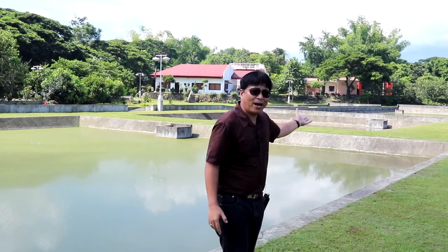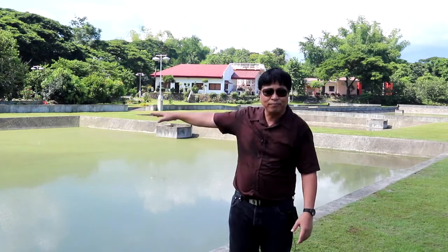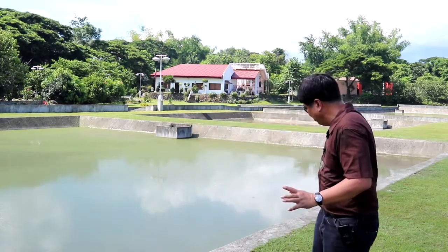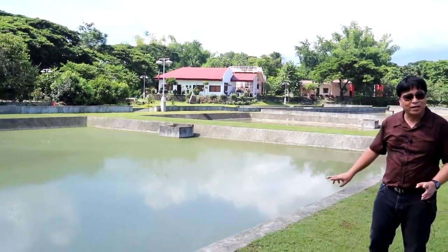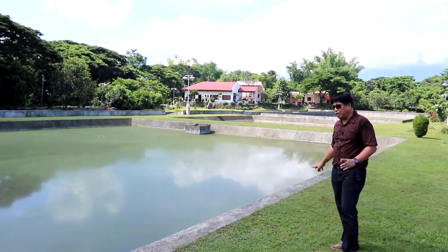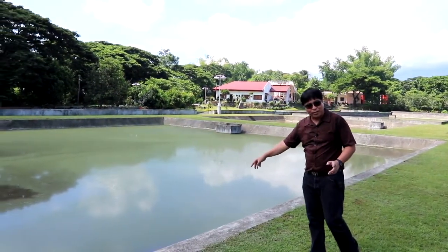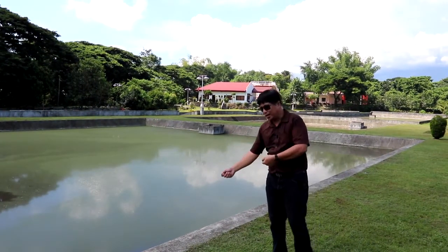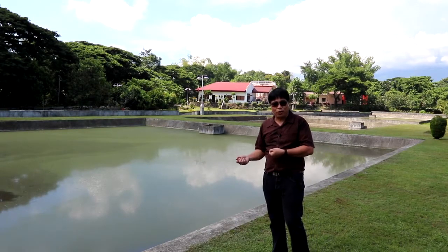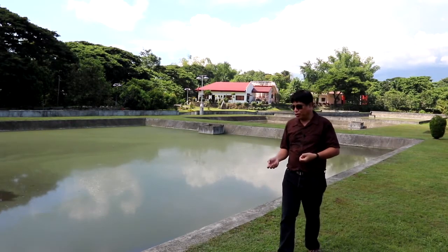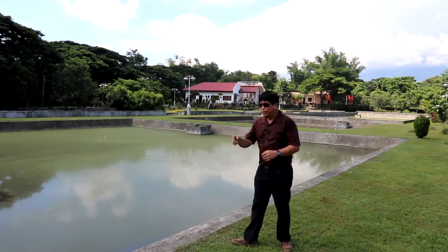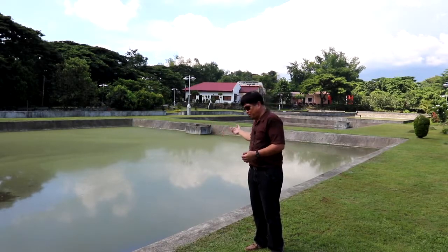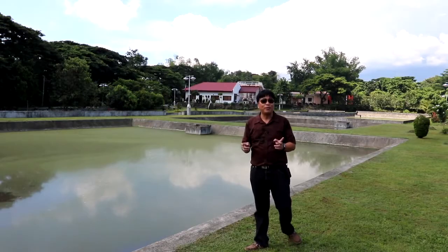So the facultative pond is a bit bigger than the anaerobic pond. To do maintenance of this, as you can see from the background, part of it is trimming the grasses, especially if you're not lined with concrete as this one, because some of the roots get into the tank and possibly cause entry of rodents as well. Compared to the anaerobic pond, this is less frequently desludged, every 5 to 10 years, but that depends on the loading.